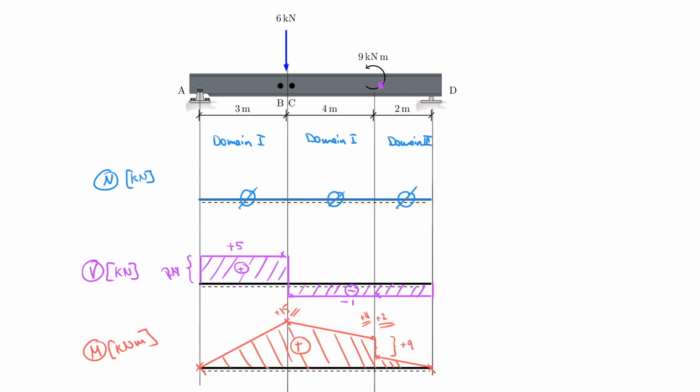And please note one thing. Yes, we said before that V is equal to dM/dx. That is something that you memorize from now on for good, because it's very important. And it is true, but remember the problem that you have if you do it the other way around. So what do you do from the shear force to the moment? You actually integrate in this direction, right?